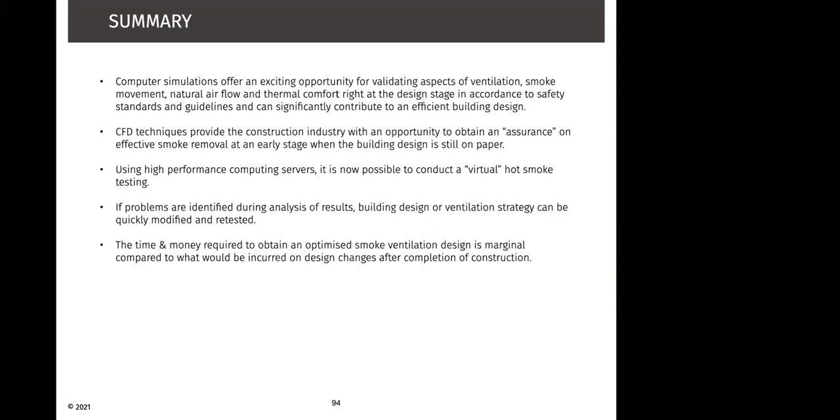So with using high performance computing servers, it is now possible to conduct a virtual hot smoke testing. And if any problems are identified, you can rectify it while the building is still on the design stage. So the ventilation strategy can be quickly modified and retested.